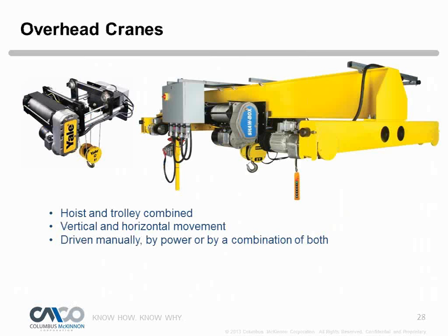And then you can see on the wire rope line, usually on the wire rope hoist, the trolley is incorporated with that wire rope hoist. So you can see it's a combination, sort of like the Yale Global. You can see the trolley and the hoist are all one unit. So you would just need to know the flange, the beam size that you're going to put it on, or the bridge that you're going to be putting that on, to be sure that it can be sized properly for that application.